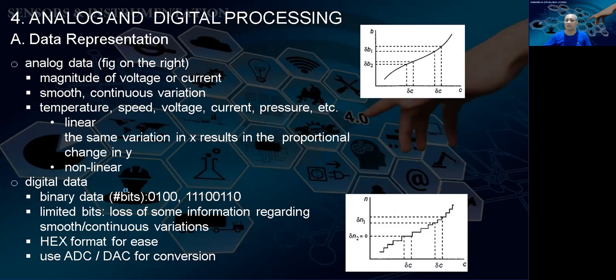If you see the picture here, the graph here, why is it like stairs like that? Because when the data is measured at one point, and then there is a sampling action at the next sample, before coming to the next sample the value just stays. That's why it is a horizontal line, and when it reaches the next sample, it will go to that point, and then before another sample it goes straight horizontal again. That's why it looks like that.